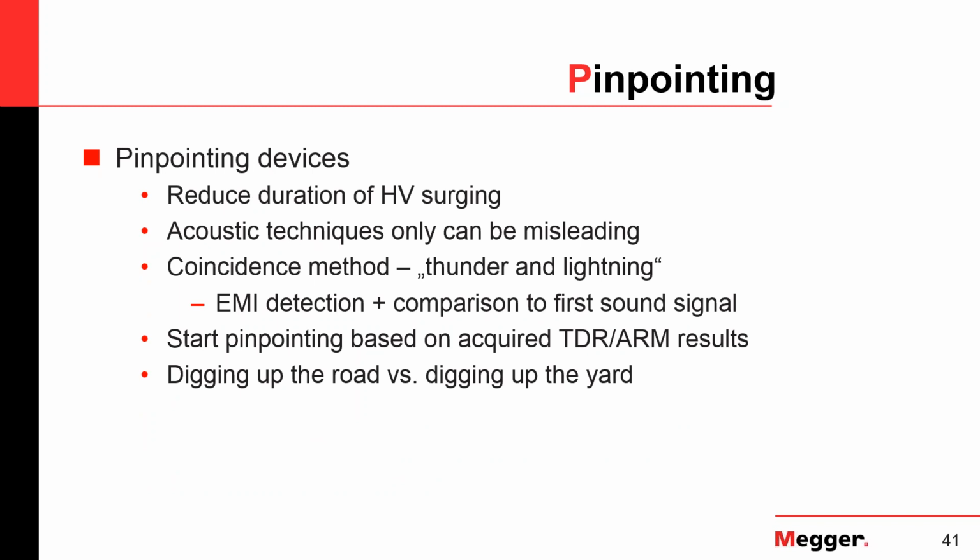Now, pinpointing devices. Why are we doing that? Technically, you could just thump with a high energy, and you can thump for hours or days, and you can just walk along the cable until somebody picks up the noise somehow. Well, this is not a preferred way of doing that, because these thumps are done typically at a fairly high voltage. So the longer you stress the cable, the more you risk getting into something.